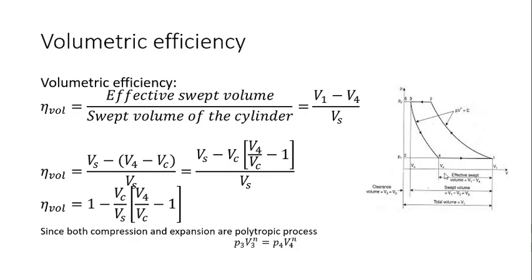that is, what is effective swept volume? Effective swept volume is from V1 minus V4, right? So which is equal to, this is the swept volume minus this volume, that is V4 plus Vc.